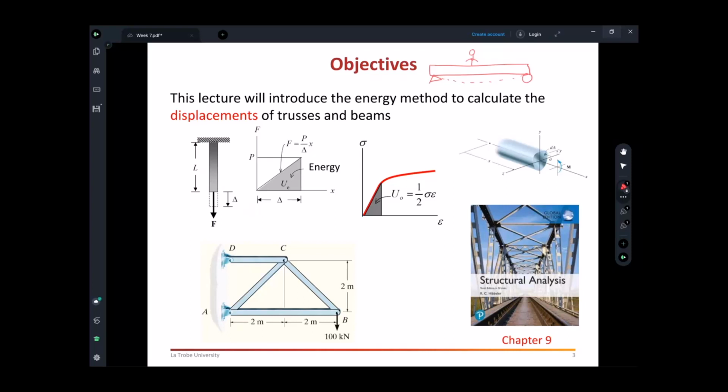So this deflection comes under serviceability, because you don't want to design something that is just jumping up and down all the time when you walk on it, right? You don't want to design that. That's the comfort of the users. That's the displacement. This is just to make it comfortable, so our users don't feel vibrating and jumping up and down.